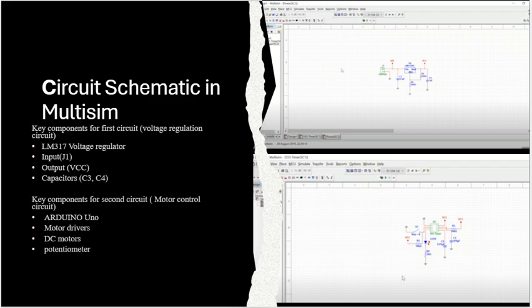And obviously, the DC motors. We'll be using 4 motors, and each motor has a task. One of the motors will be for the shuffling of the cards. One of them will be for dealing using the precision roller mechanism, and 2 for the controller's arm to grab and organize the cards. We'll also be using the potentiometer, allowing manual adjustment of motor speed, aiding the fine tuning during testing.